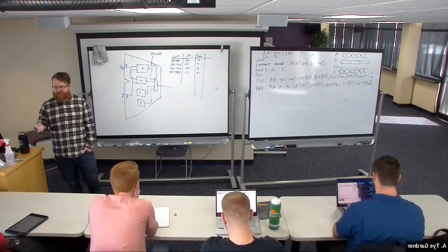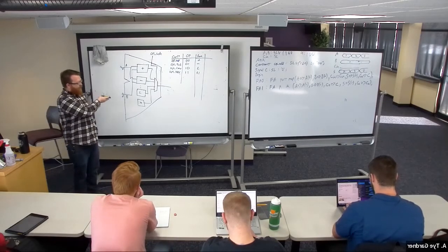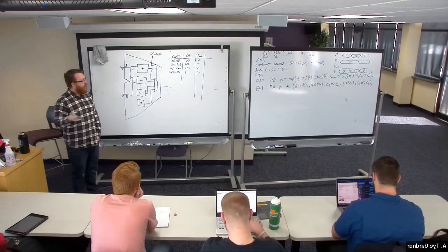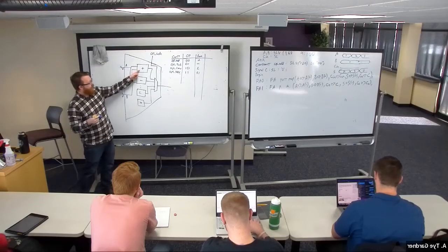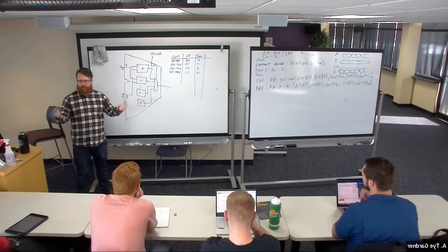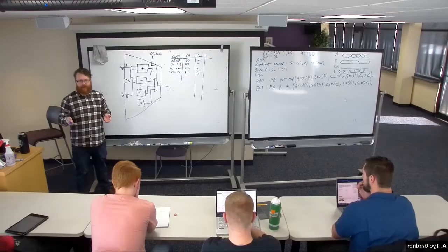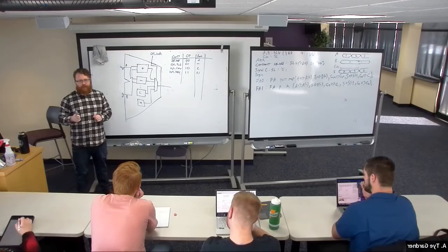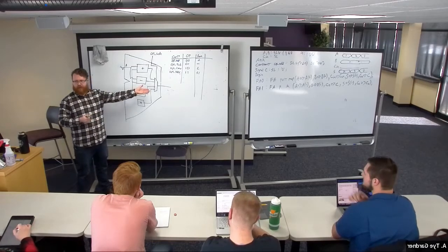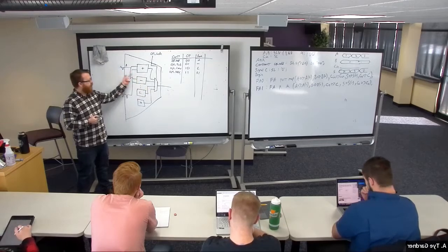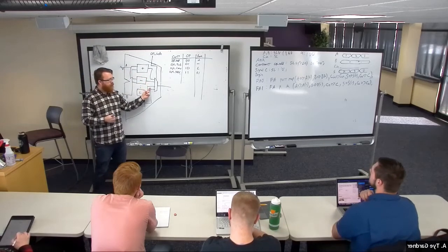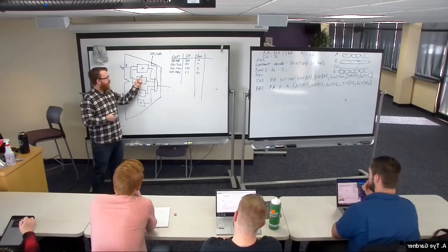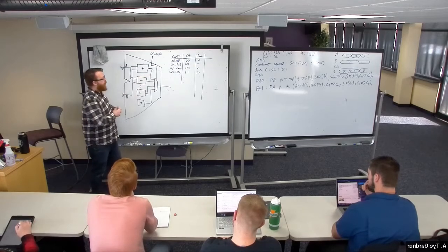The whole trick of this is being able to look at a picture like so and turn it into code, right? You're going to write 4 different sources. One of them is going to do 8-bit addition, one of them is 8-bit subtraction, one of them is load, one of them is hold. You're going to build a mux using when else, just like I showed you. It's going to take the outputs here. These each need to be their own intermediate signal names, right? Because they don't leave the ALU. I have to declare them as signals. They need to be the right size.